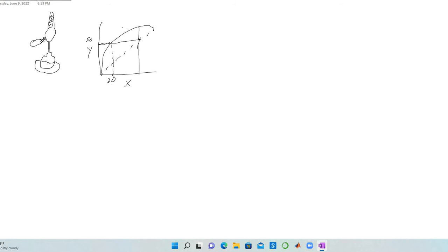We flash it, come over here. Now Y is at, I don't know, we'll call it 75%. And then we'll intersect the 45, go down, flash it again, and so on and so forth. Now, this is the basic idea of what distillation is. Except in distillation, we're going to save a lot of energy by not having to condense it at each step.